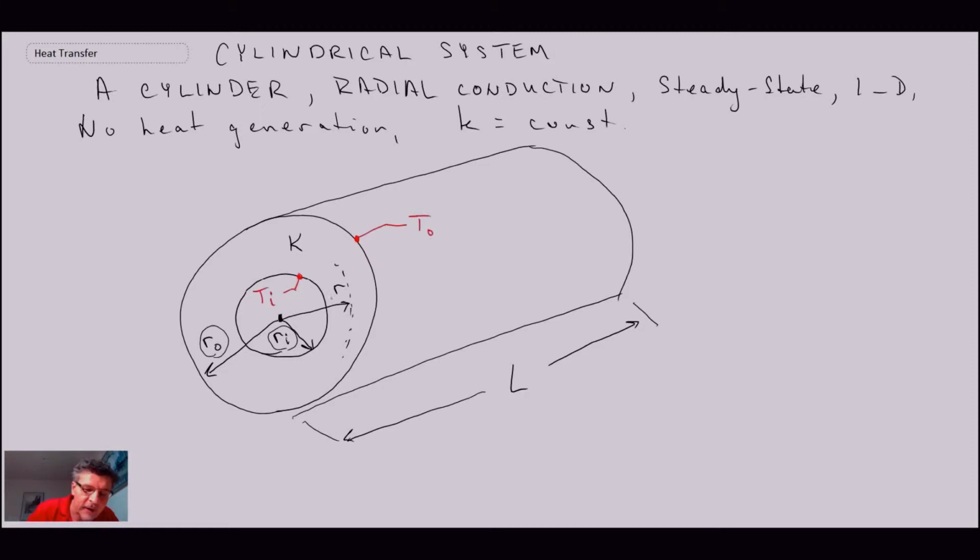And we're trying to determine temperature at some given location. Our thermal conductivity, we're told, is K of the material, and Ti and T outer are the boundary conditions for the temperature. The area, in terms of what the heat flux is going through, is going to be the circumference of this cylinder at a given radial location R multiplied by the length, and usually you do per unit length. But anyways, that is the scenario that we have.